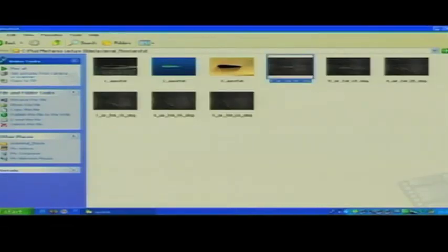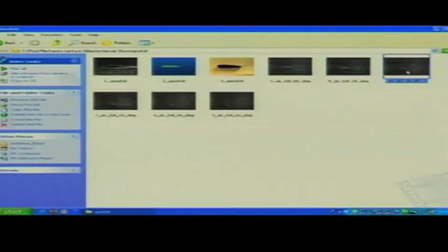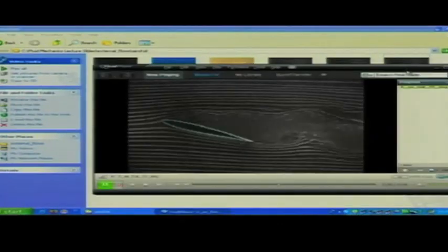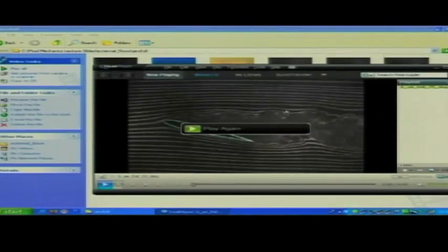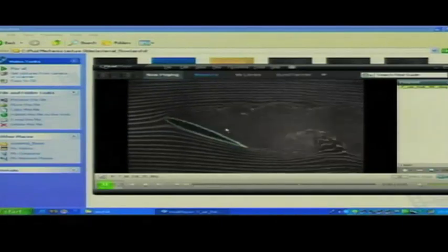Now we will see the effect of different angles of attack. This is an aerofoil section where you have 0 angle of attack. Now let us say 15-degree angle of attack. With the increase of the angle of attack, you see what is happening. You see a flow separation taking place quite quickly. Whatever is that circulating region, that is a region of low pressure beyond the separation. Look at higher and higher orientations: the effect of the separation becomes more and more severe.